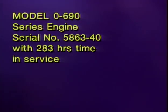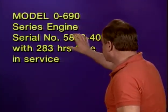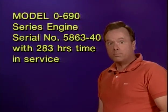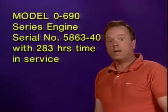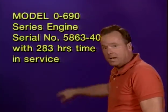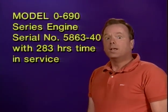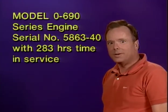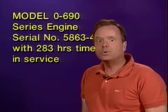So what is the answer to this question overall? Do we have to comply? And the answer is yes, we have to comply. Now, we don't have to comply with A because it's outside the range of serial numbers, but we do have to comply with B because it does apply to that range of serial numbers that we're in here. And we have to comply with Part 1 of B because the engine does have more than 275 hours time in service. It has 283 hours of time in service. That means we comply within 25 hours. And what do we have to comply with? We have to comply with C down there at the bottom. C, nothing to it.